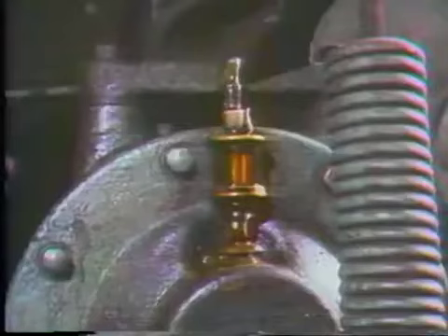Filters keep the oil clean by using a filtering medium, such as bags or screens. Coolers remove heat that the oil picks up from the bearings. So, a forced lubrication system actually accomplishes three things. It lubricates the bearings, it keeps the oil clean, and it keeps it cool. There's usually a sight glass on the oil reservoir. If the oil level gets too low, oil has to be added.